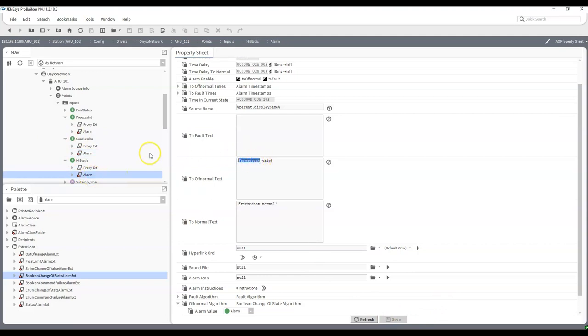And same thing for my high static. Okay. Well, now I'm going to set my temperature sensors with the out of range alarm extension. And I can apply the same thing to my humidity and my static pressure sensors, but just to show you here how to set up at least one of these out of range alarm extensions, I'm going to do just the space temp sensor.